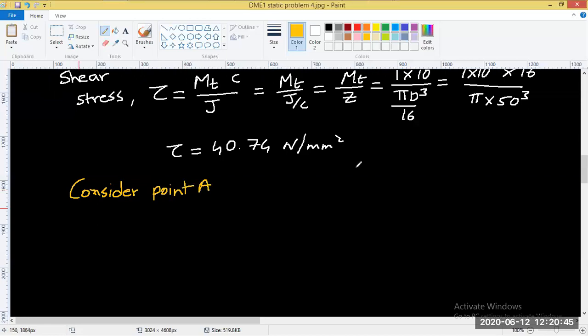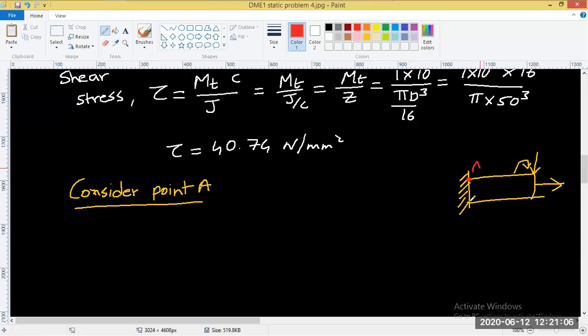So there are two sections. You have the bar being like this, right? Because of the loading conditions, the torquing, the axial load, the bending load, all these things, two portions are created. The critical portions are created like this. This portion here will be A, and this one is B. These are the critical points where the failure might occur. So first off, we'll start with A.